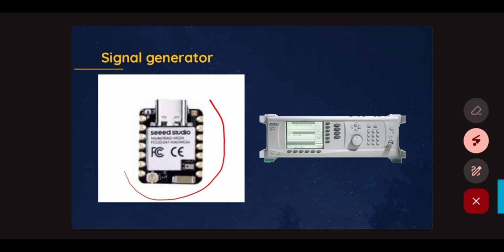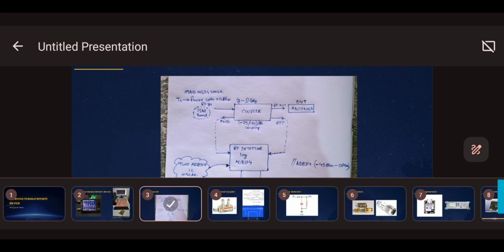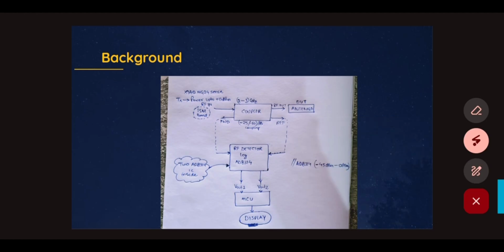I have this Seeed Xiao microcontroller, and over here I have this UFL antenna port. From here I can get 2.45 gigahertz, and usually I deal with the 2.45 gigahertz ISM band, and I was going to feed that. I understand there is a 50 ohm characteristic impedance and all, so I will definitely consider that.